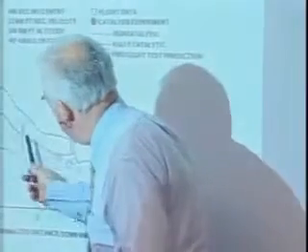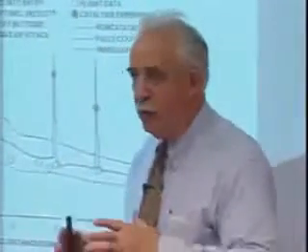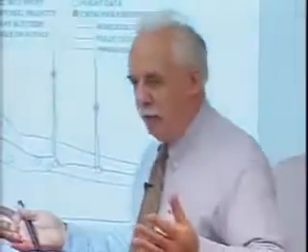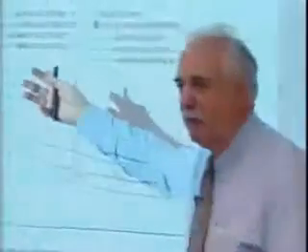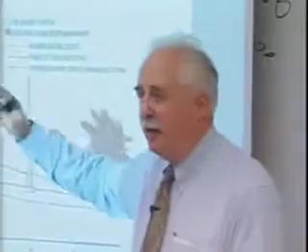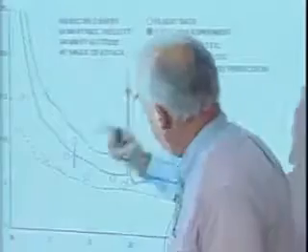I don't remember what the measurement problem here was. And here's this point way up front. You can see again, this is a viscous flow field where we could do the chemistry, but we couldn't do the fluid mechanics real accurately, okay? This is still a mix and match. Look at the difference between the measurement and the prediction. Same thing as before, only I eased it by showing temperature instead of heat flux, okay? The surface catalysis is the predominant factor.